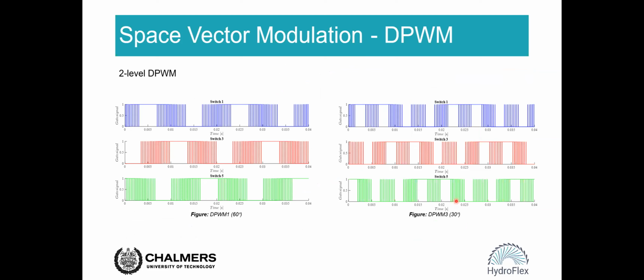And there are some other kinds of discontinuous PWM as well. On the left side of this slide is called discontinuous PWM1. The difference compared with before is we can see each phase or each switch is clamped to the positive, and here negative rail of this link alternately in one fundamental period.